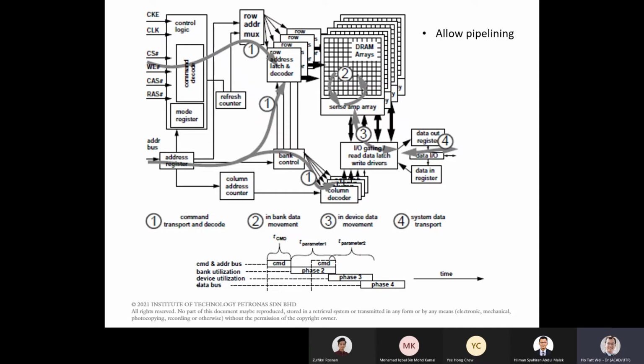But this SDRAM interface design is not easy, it's not trivial, for most of you. For me, it's not that difficult, but for you, it's probably because you're still learning how to do that. So I'm showing you this because these numbers show you the sequence of steps. And here is basically a timing diagram. Why? Because it's trying to show you, number one, there are timing parameters. There are a certain number of microseconds or nanoseconds you have to observe when you're interfacing with the chip, and this is actually showing you which part of the SDRAM circuit is being utilized.